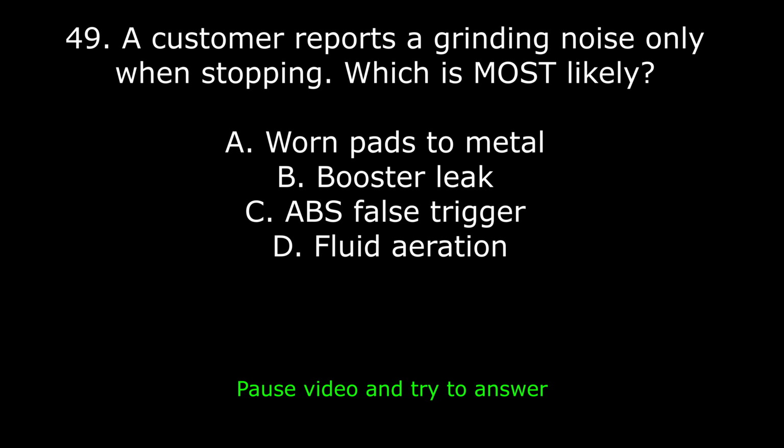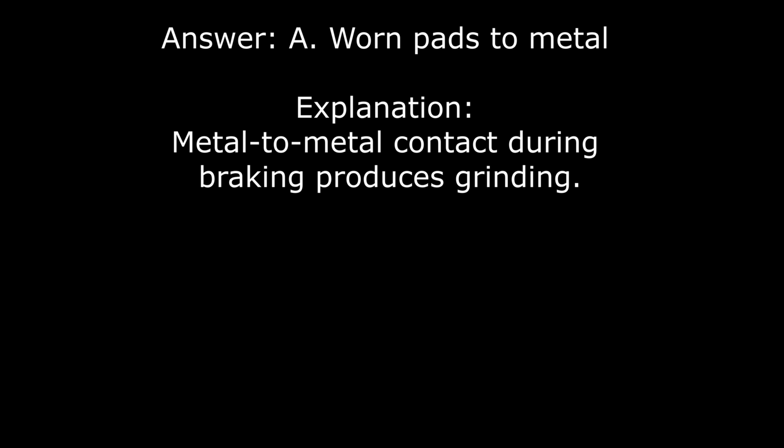49. A customer reports a grinding noise only when stopping. Which is most likely? A. Worn pads to metal, B. Booster leak, C. ABS false trigger, D. Fluid aeration. Correct answer is A. Worn pads to metal. Explanation: metal-to-metal contact during braking produces grinding.